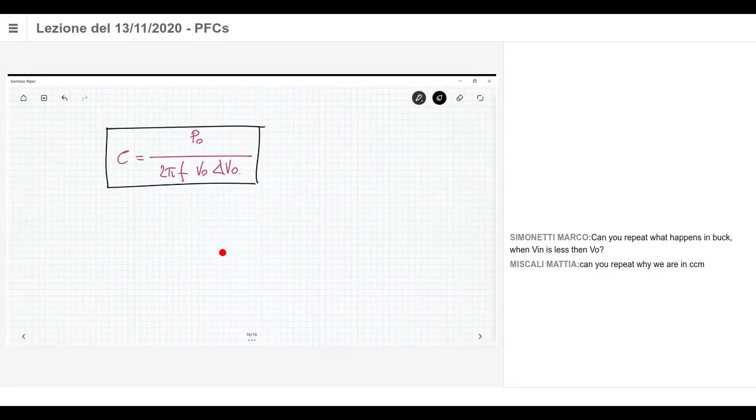And the switching frequency is, let's say, 100 kilohertz, 200 kilohertz, 500 kilohertz, in a region of frequency in which the electrolytic output capacitor is no more a capacitor, it is a resistor. Remember, it acts like a resistor, which is called ESR, because the switching frequency is large.